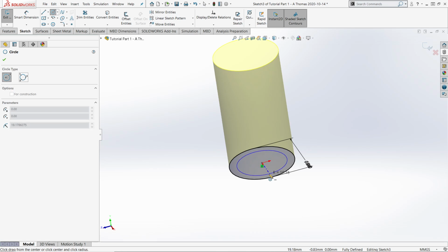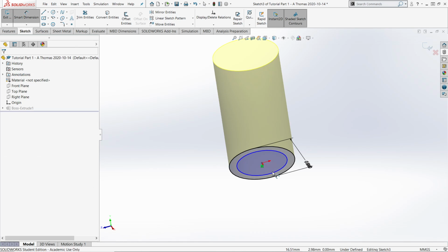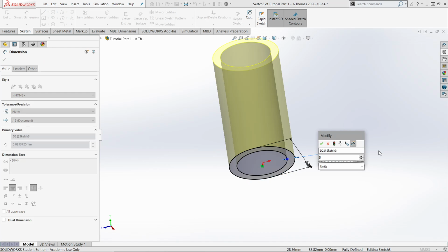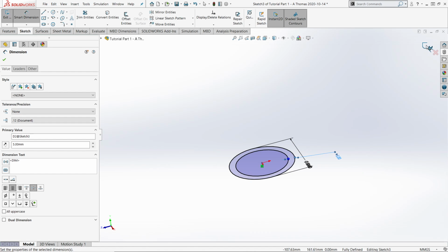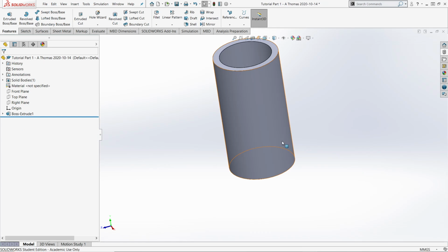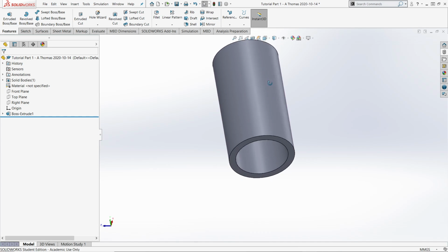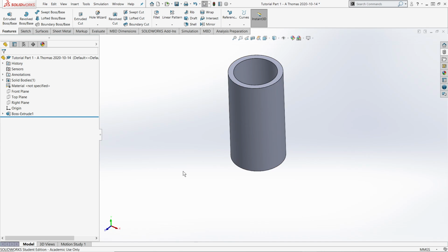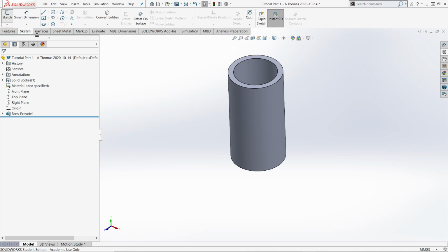I can make a circle, do that thickness dimension that I wanted, make that 5 again, 5 millimeters, and then exit the sketch, and it'll update it with having a hole inside of it. So you can do that all at once. So I could draw a plate, right, and I could have the cutouts for accessing buttons or switches. I could have that all in one drawing. I'm just going to show that really quick.